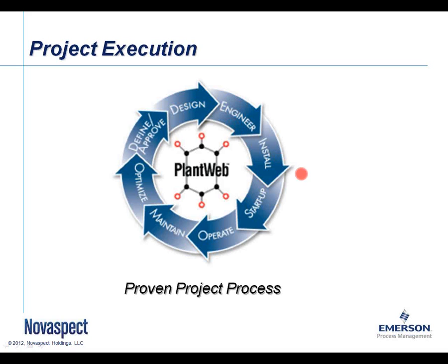This is then followed by the installation phase. This is where essentially the hardware meets the field. This is where things get installed. We get things installed, checked out, and then we move into the startup phase where we go through the commissioning of the new controls, any new instruments, calibration verifications. We get into tuning, adjustments of combustion curves, and then ultimately we go back to operate.